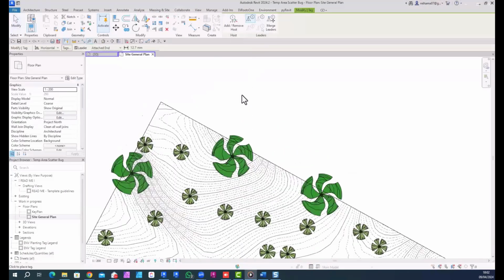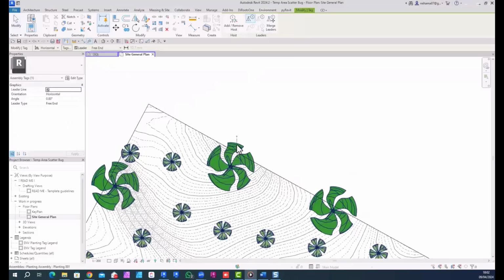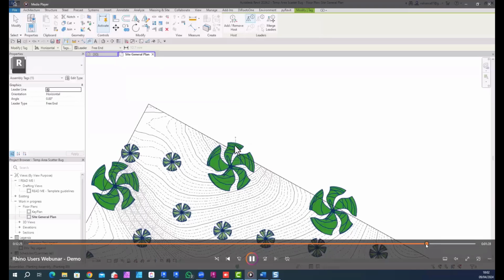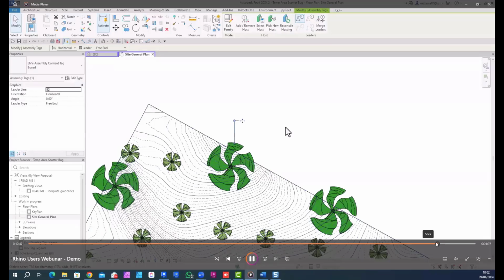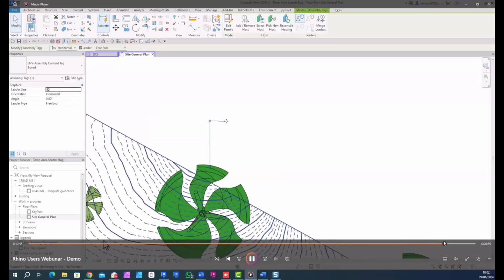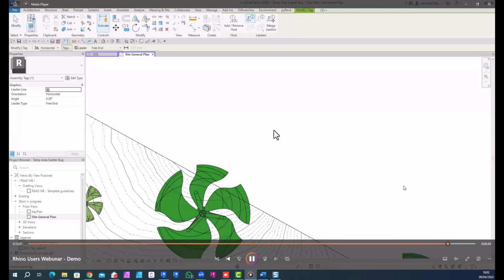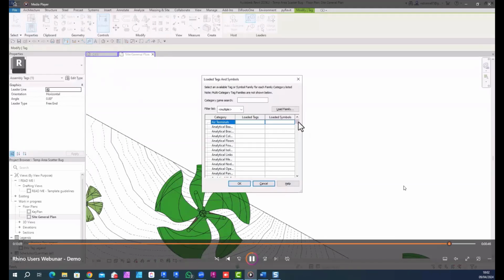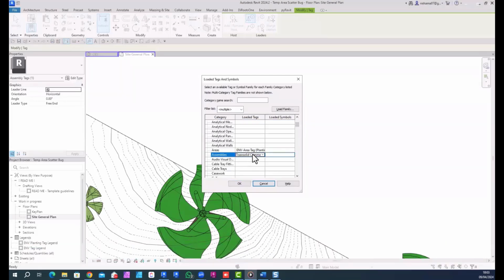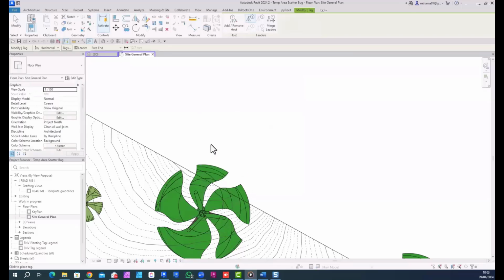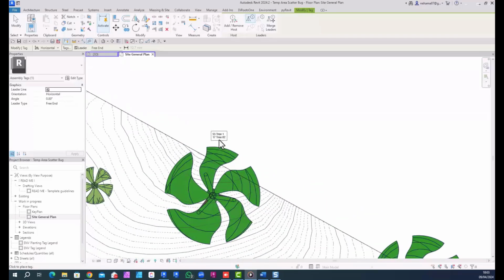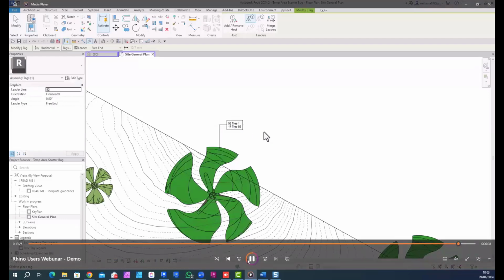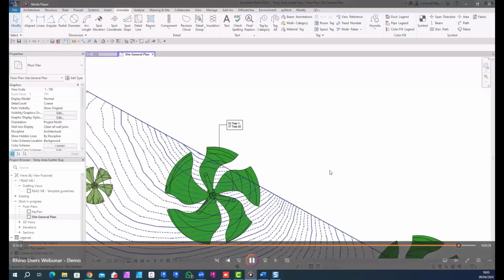And now what I'm doing, I'm just using the same assembly content parameter, but over here I got the wrong tag, so I didn't exclude that from the recording. Let me just take the correct tag. So the tag should include the assembly content parameter within it. Don't worry if you don't have a specific tag, because when you're using Environment, we provide a default tag that you can later add and make your own. But over here, I can actually tag these tree assemblies, and then I know I have 53 of the first species and 17 of the second species.